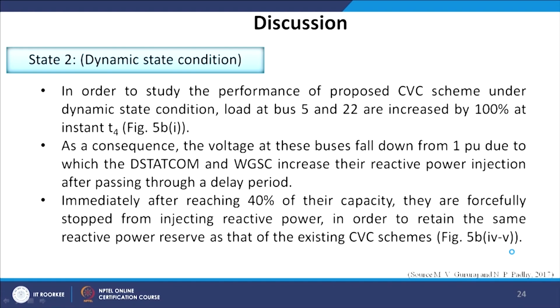Immediately after reaching 40% of their capacity, they are forcefully stopped from injecting reactive power in order to retain the same reactive power reserve as the existing CBC schemes.